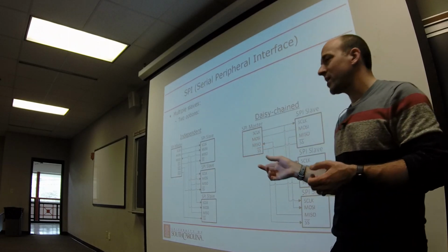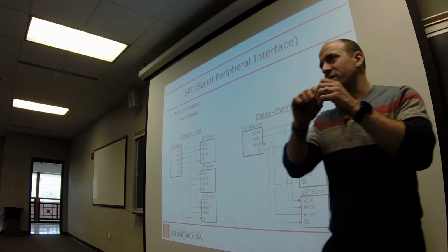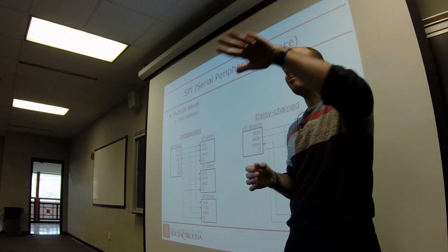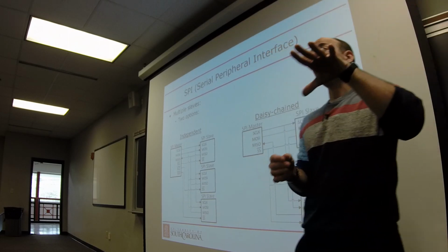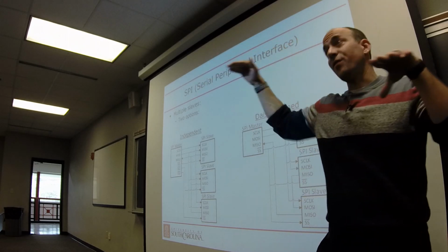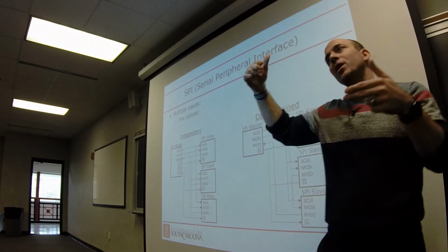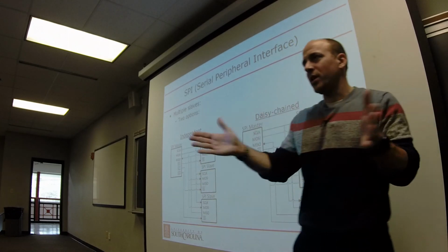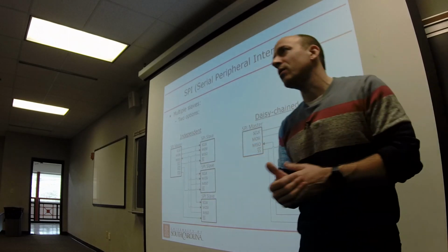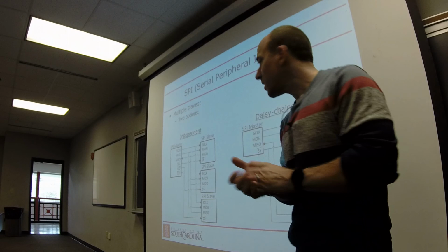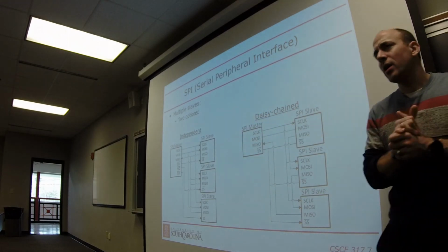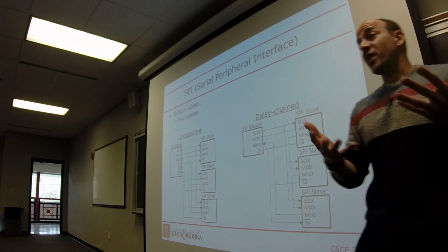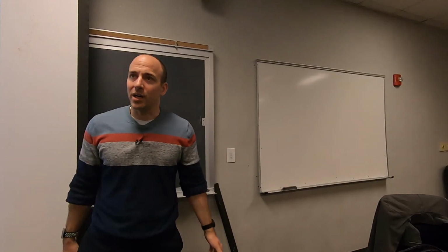Although, as I described last time, it's not really true because it's not a linear relationship between the PWM duty cycle and the brightness, because at the bottom, at really low PWM values, it's basically off. And once you get beyond like 70%, I think it's at full brightness. There's a linear region sort of in the middle, but I don't think we're requiring you to work all that out. You can just assume that it's 0% to 100% on the PWM. Does that answer your question? I was just wondering how you light up the bulb at like 30%. Yeah, you just essentially send an analog value, but it's the fake PWM analog value.